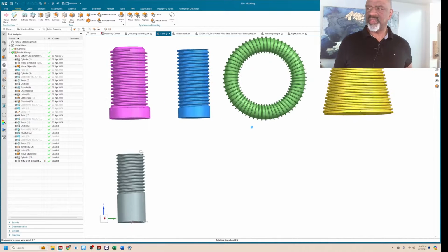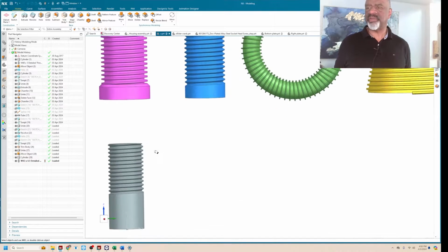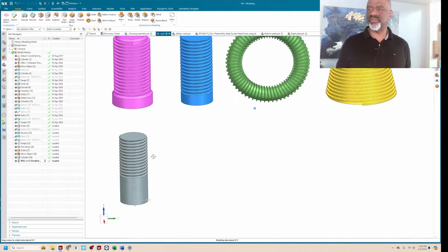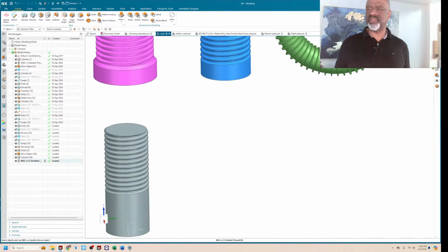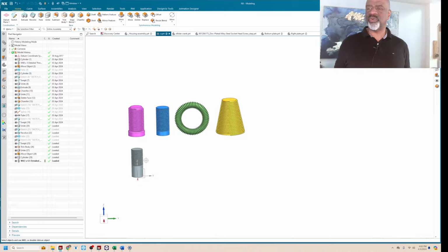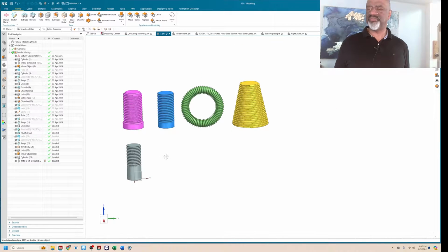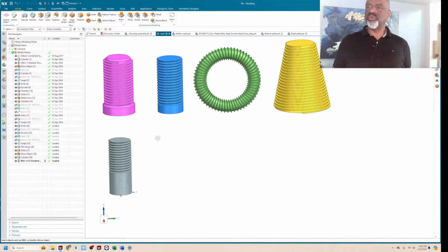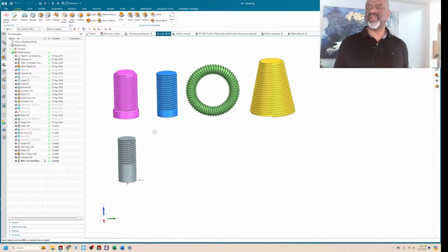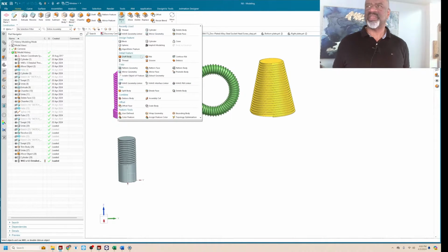Say okay. So it's important that you match up the diameter of the cylinder with the thread, because it's basically going to cut into whatever cylindrical surface that you give it. So that is one way to do threads very quickly. Very nice. Of course, lots of times when you're doing threads on something, it is best to give it symbolic thread if you can, if that's okay for the application that you have.